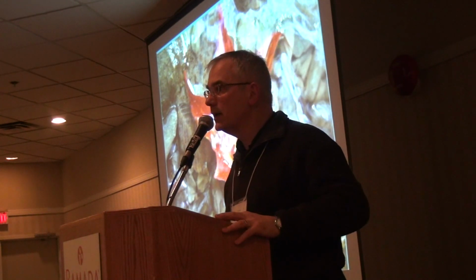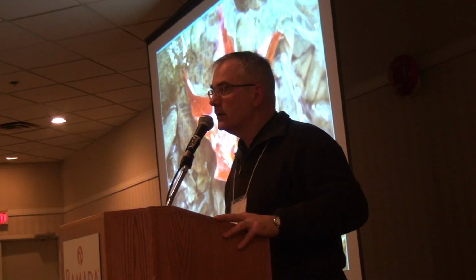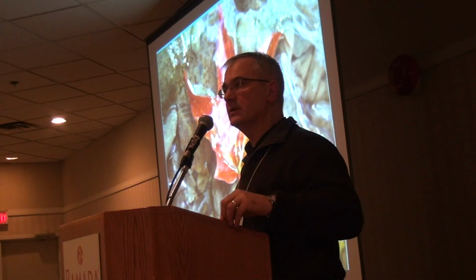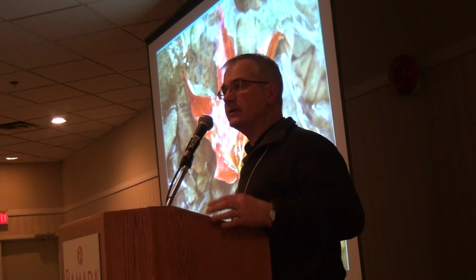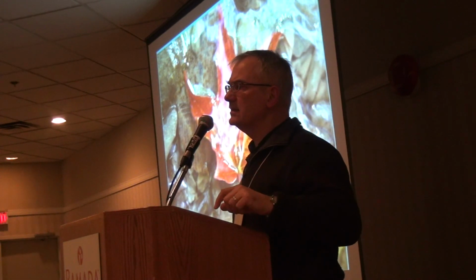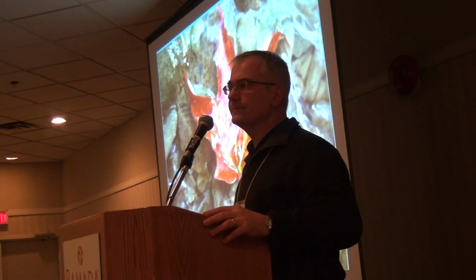Scott? Yeah, I was fascinated to see that your cabinet was so effective in removing the particles. Could you elaborate on the mechanism, and how did that appear to remove the micro-size particles? Yeah, so the way the filters work, those are high efficiency particle filters. So they're pretty standard in any sort of clean lab environment. And they remove, I think, 99.9999% of the particles larger than a half a micron.